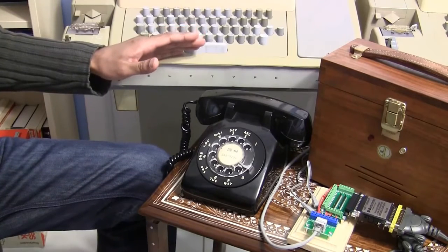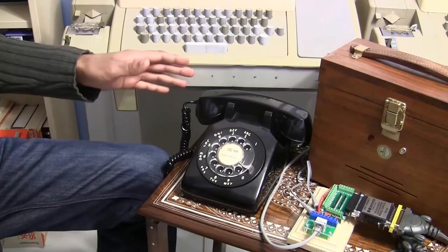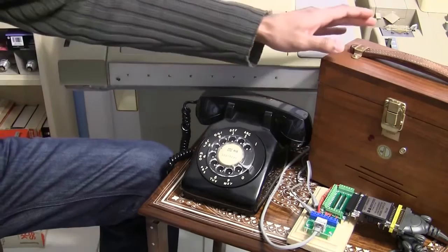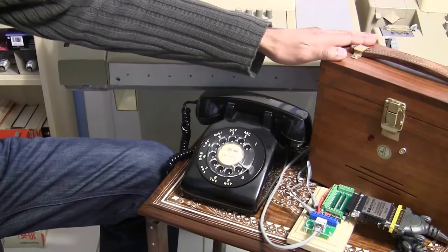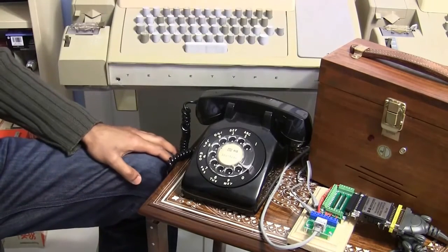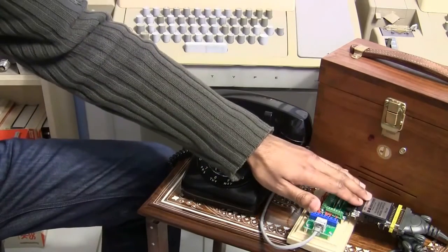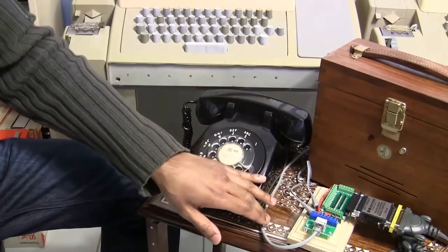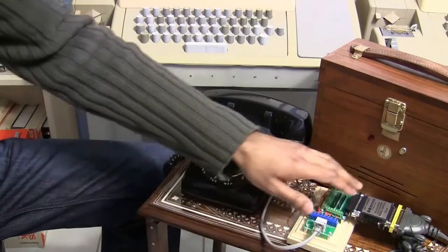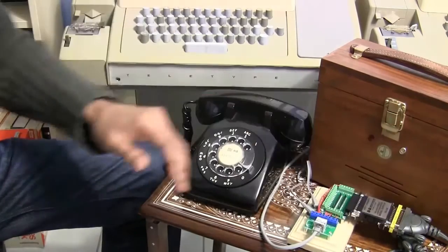Now, the ASR-33 teletypewriter operates on a 20 milliamp current loop, so the presence or absence of current would signify a 1 or a 0, whereas our Livermore modem operates on the RS-232 protocol, where voltage levels would indicate a 1 or a 0. We're going to need some way to convert this, so we have a loop converter. Running from the teletype over category 5 cabling is our 20 milliamp signal, which is fed into one end of the loop converter. On the other end, we have a null modem cable, which is run to the modem.